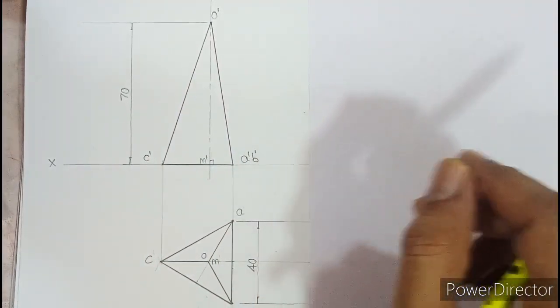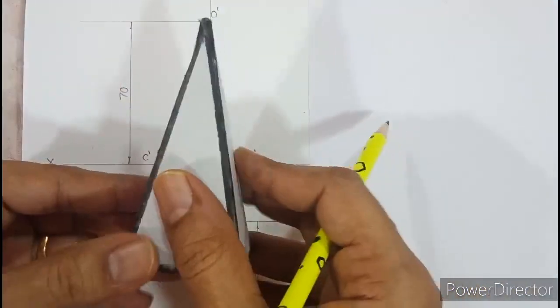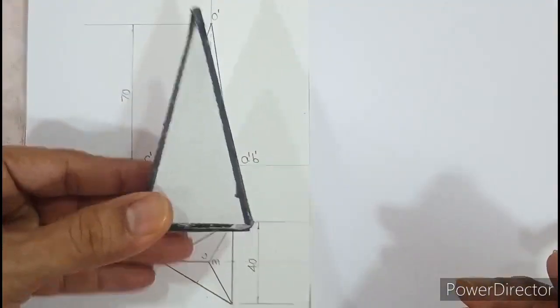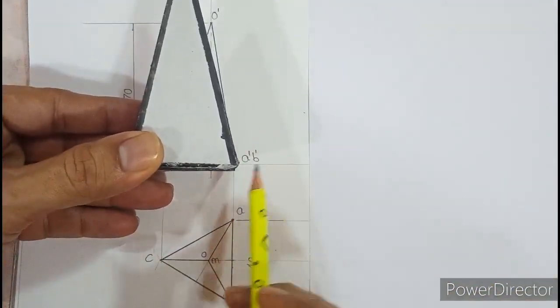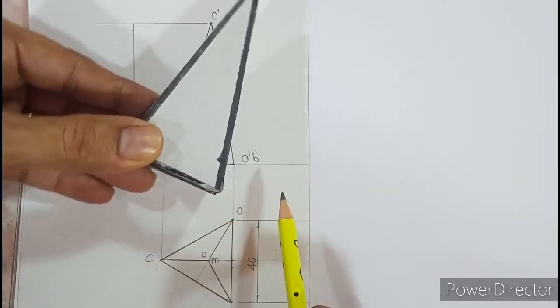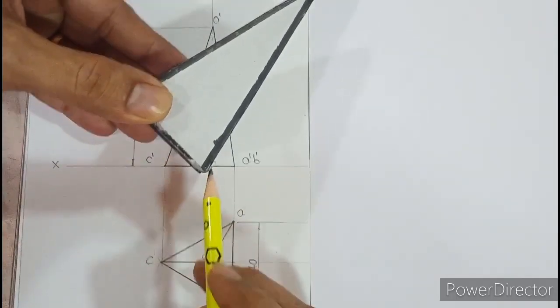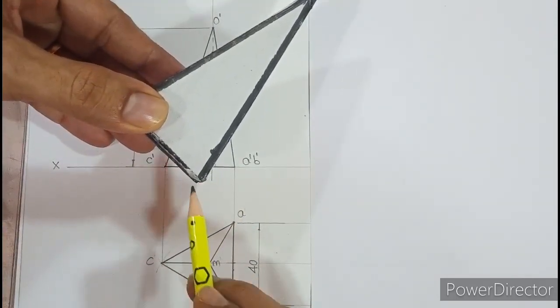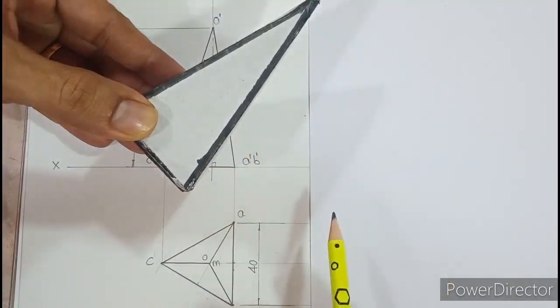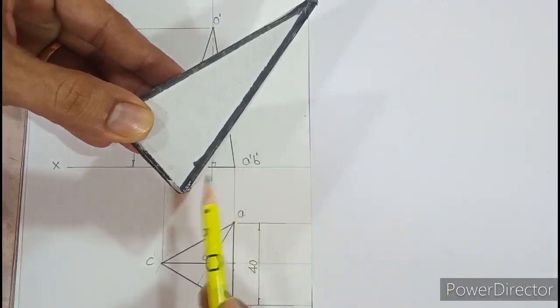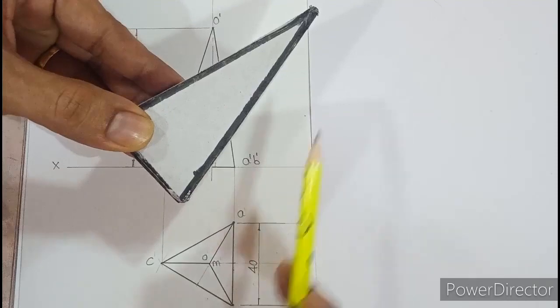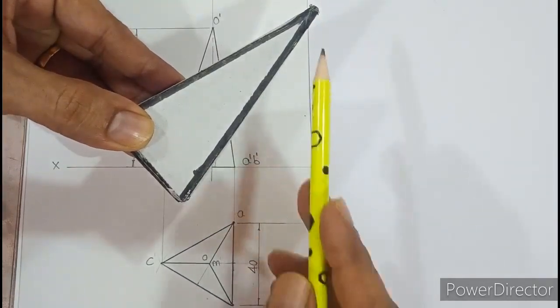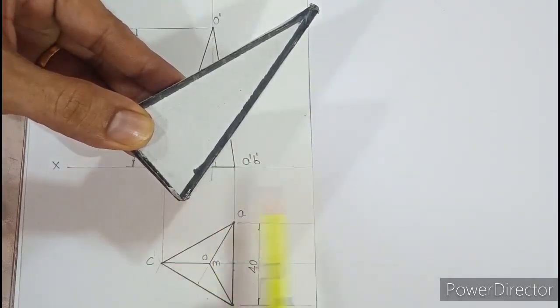So as a special case, what we need to do next is, suppose this is that triangular pyramid. Now in the second stage, I need AB on XY. So tilt such that if you look at the projector of AB and projector of O, that horizontal gap should be 20. So if you project O and AB, the horizontal gap should be 20.